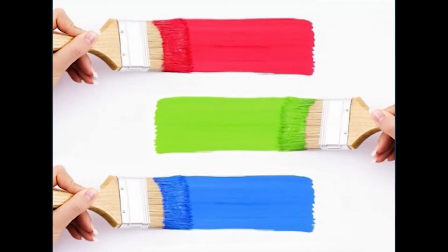They are composed of tiny solid particles less than even 1 micrometer in diameter, a size that enables them to reflect light. Now, visible light has a wavelength between 0.4 micrometer and 0.7 micrometer. It imparts color and opacity. Pigments render a characteristic finish to the paints and protect the surface underneath from corrosion and weathering. The three main functions of pigments comprise the optical function of providing color, opacity and gloss, protection to the subsequent layers, and a reinforcing function which helps the binder in proper adhesion.